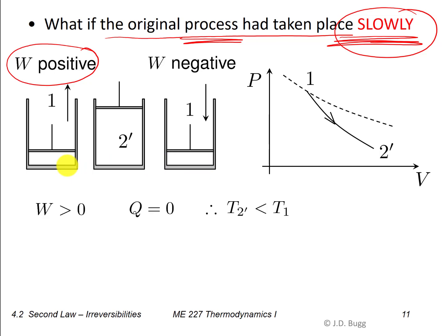And what will happen on the PV diagram is we're doing an adiabatic compression. Notice no heat transfer during this stage either. And so we're going to follow back along exactly the same line. The temperature is going to increase back up to its original value, and the pressure increase back up to its original value. And notice that there's no net change in the surroundings either.